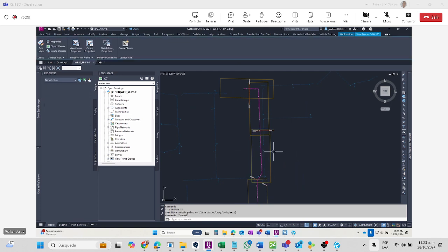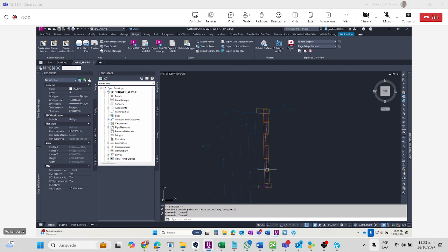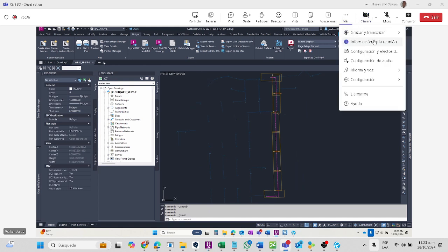Okay. So basically, this is what our view frames are currently and where our match lines are currently. We haven't created the sheets yet, but it used that template to give us our limits for our plan view. So any questions on this before we create sheets? Okay. So I'm going to hit save here. And then the next step is create sheets.